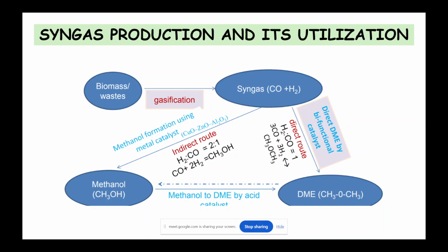In combustion, you will have more carbon dioxide, from more complete combustion and oxidation, so more carbon dioxide and water vapor. Whereas in gasification, since there is a controlled supply of air, apart from some amount of carbon dioxide, carbon monoxide and hydrogen gas are going to be very dominant. They are going to be the major constituents of the product gas mixture. In pyrolysis, it is typically going to be CO plus H2, and other forms of carbon, such as solid particles, are going to be present.